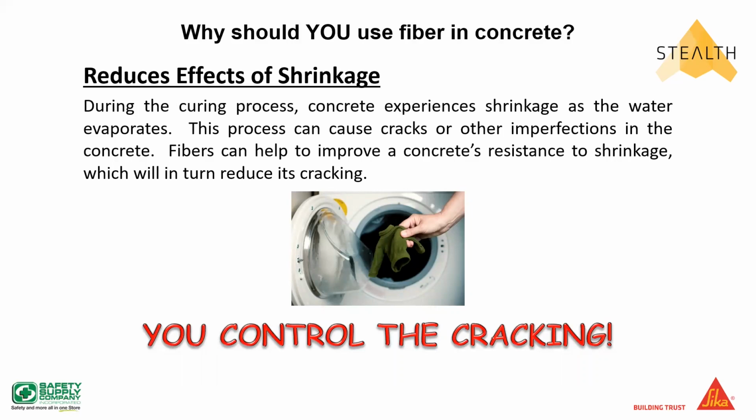If we can control the shrinkage in the mix, we can control the cracking of the concrete. Now, not everything in the mix is shrinking. Your stone's not shrinking, your sand's not shrinking, but what is shrinking is your paste, your cement. If you've got fly ash in the mix, it's not the part that's shrinking, but it's the cement that's shrinking. So we try to control that.